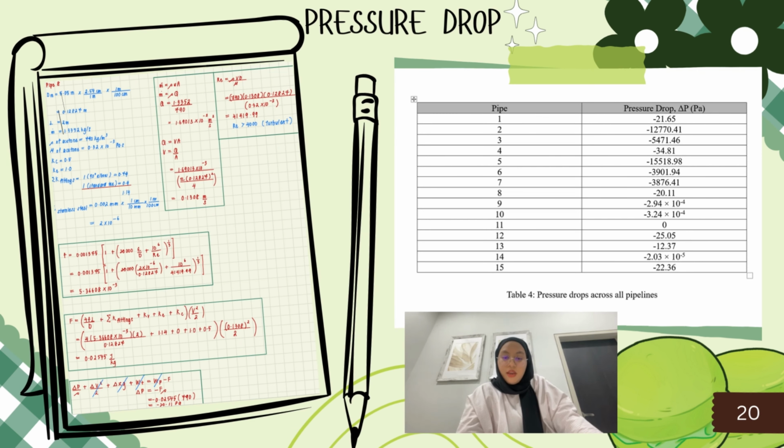Along the pipe, I use the same calculation method for all the pipes in the system up to pipe 15, applying their respective mass flow rate based on the process flow diagram. This ensures that every section of the system is analyzed for pressure drop consistently.